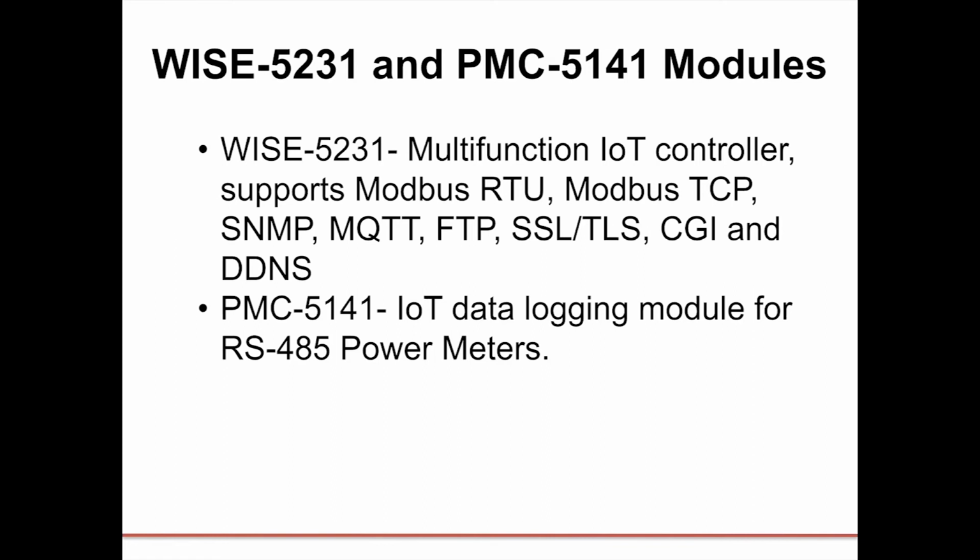It allows you to connect to our smart power meters over RS-485 to read power data of the devices, then save the power data, send the data to a backend FTP server, SCADA, or IoT platform for further data integration and analysis. PMC 5141 also provides power demand management and alarm notification functions. It has a built-in web server, which allows users to connect via browser to view power data, set up parameters for the controllers, or view real-time and historical power data of your connected devices.